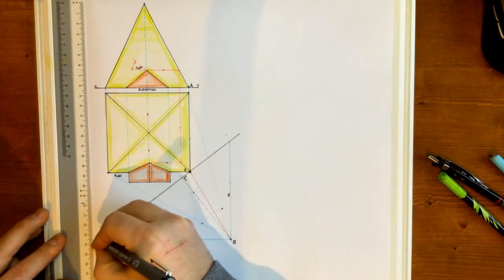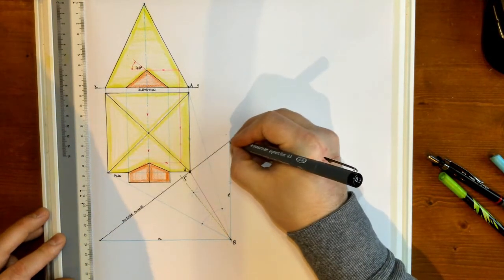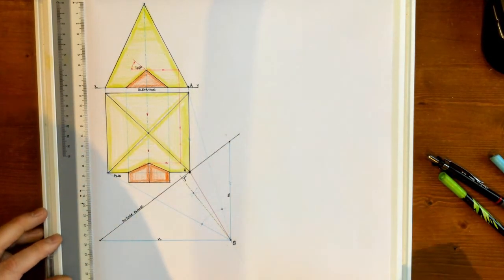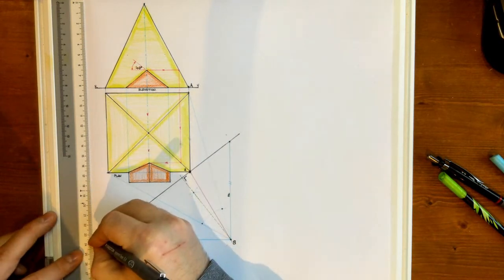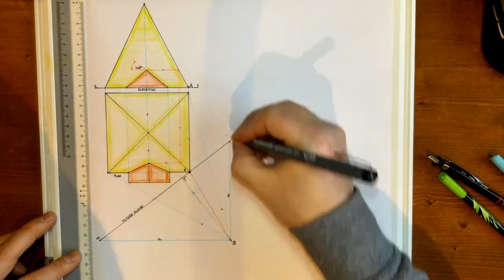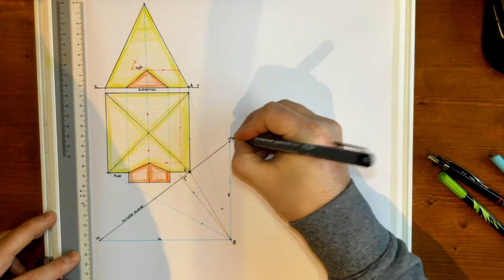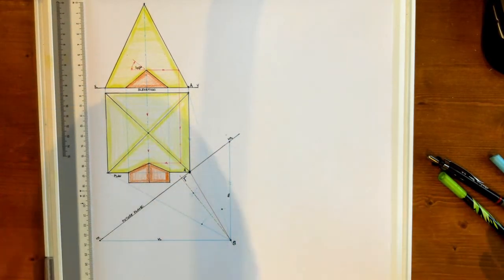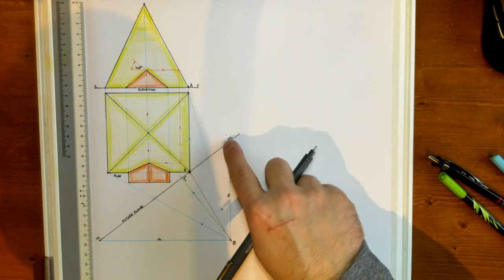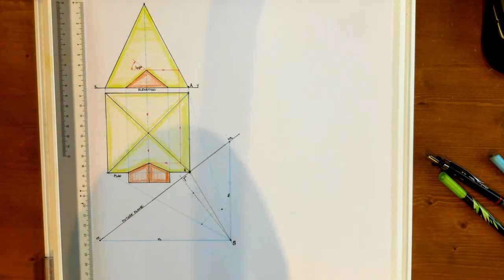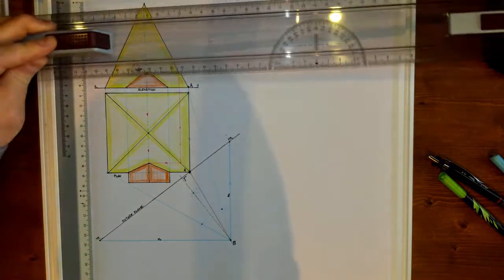And these 2 points here now, they are going to be the points now that are going to inform our vanishing points, okay? So we can actually call them VP1, VP2, but these are the vanishing points in a plan view position, okay? And we want to get them in their elevation position now in a few moments. So what we're going to do is we are going to project out our vanishing points now with our vanishing lines at a right angle to the picture plane.